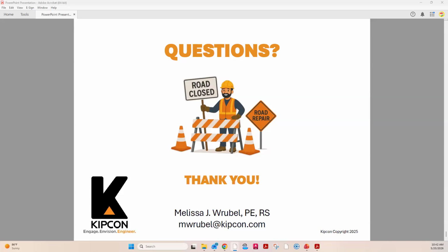Summer and fall are absolutely fine as well. In the summer, though, when you get into the really hot weather, the asphalt tends to be a little more tacky, and you tend to see some tire scuffs. The tire scuffs go away; they lay back down, but that pavement takes a longer time to set up so that people can get back on it.